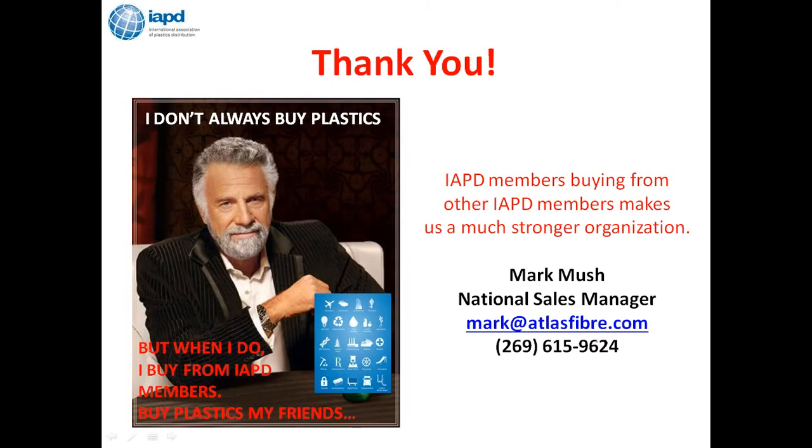Are there grades specifically recommended for outdoor applications, possible UV stabilizations? In general, these grades are not UV stabilized. For example, if you put a few sheets of canvas phenolic on a shelf in the warehouse, and an inch or two of the surface of one of them is exposed, and you go back a few weeks later, you're going to definitely find a color difference that has darkened up. And these do darken with age. You would have to go, I think, with a black material to get more of a UV stabilized result out of it.